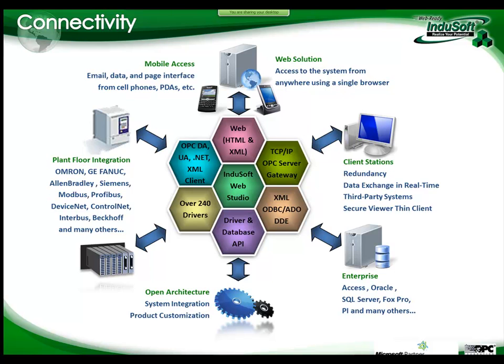And that's very interesting because I've worked on systems where the DCS actually is an OPC client of our SCADA. So we talk to the PLC, we acquire the data from the PLC using the drivers, and then we make that data available through our OPC server to OPC clients. In that case, a DCS is the OPC client.